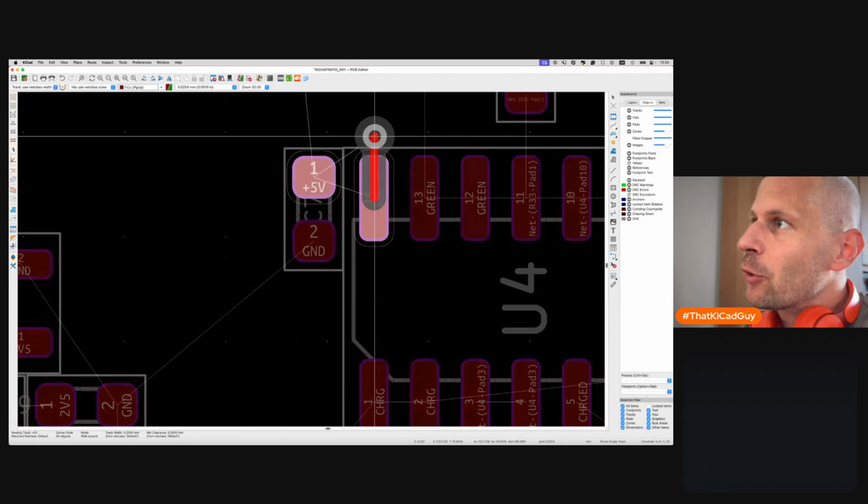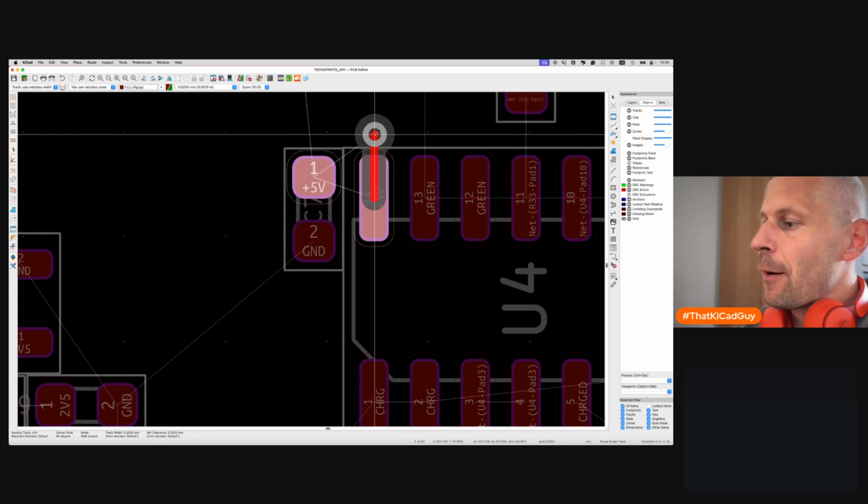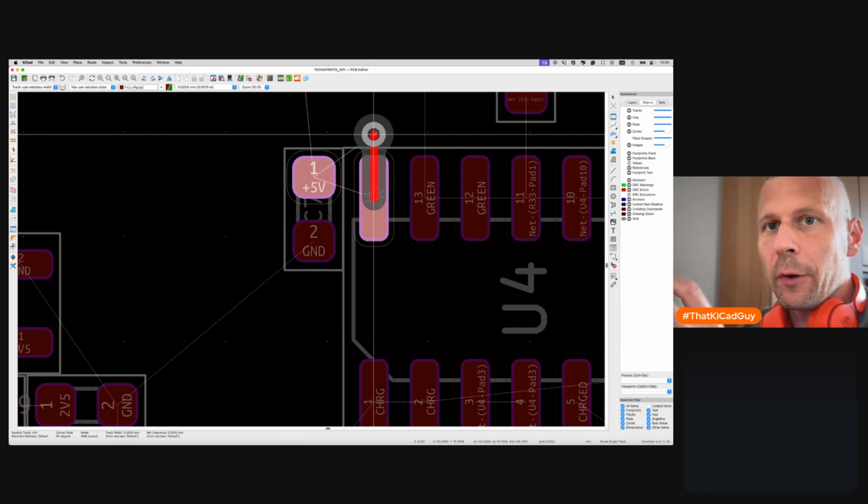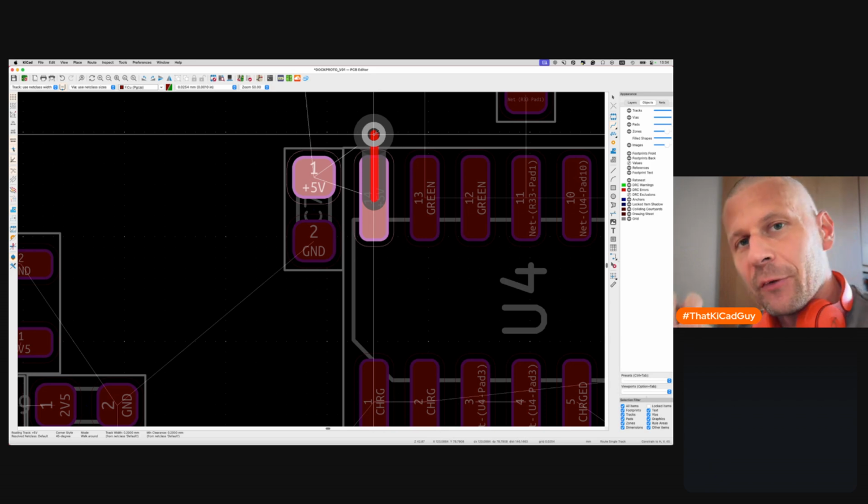So I try not to overlay the via circle with the solder mask expansion. It means that the mask will not join with the unmasked part of the via. It means that the via will not suck out the solder from the pad.